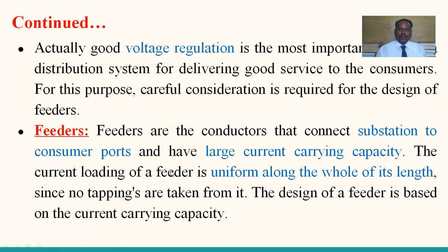So remember here, students, feeders are conductors which are connected in between the substation to the primary of the transformer, which is having a large current carrying capacity. So the current loading is also uniform along the whole of its length. So no tappings on this.